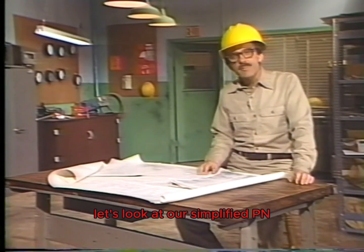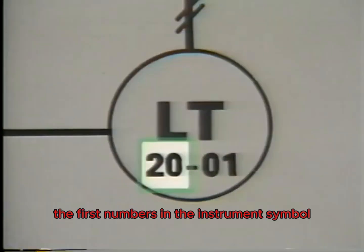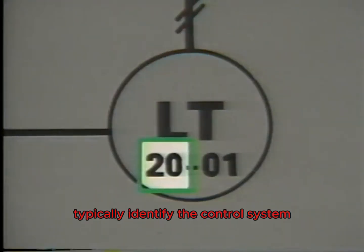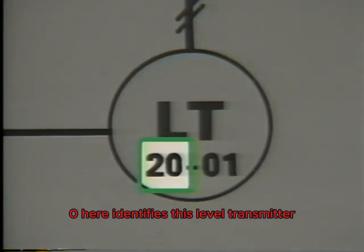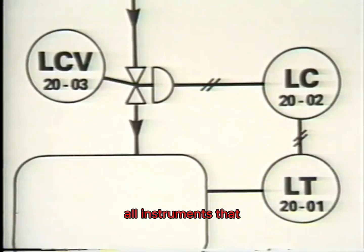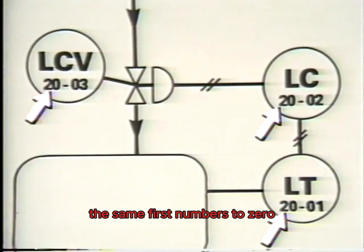Let's look at our simplified P&ID to see what the numbers are for. The first numbers in the instrument symbol typically identify the control system that the instrument is in. For example, the number 20 here identifies this level transmitter as being part of control system number 20. All instruments that are part of this control system will be identified by the same first numbers, 20.